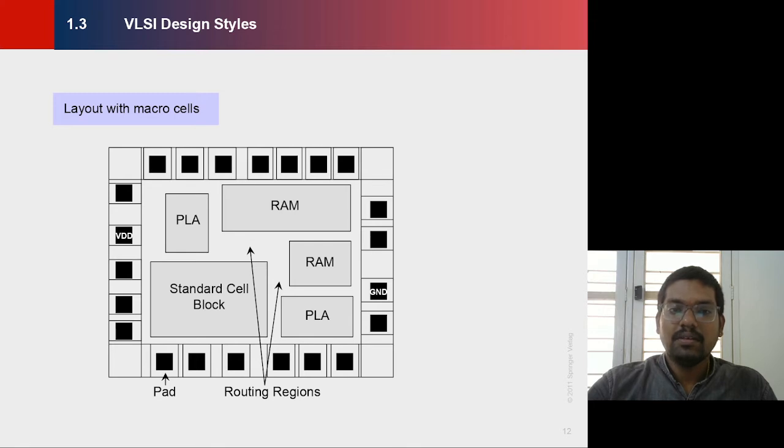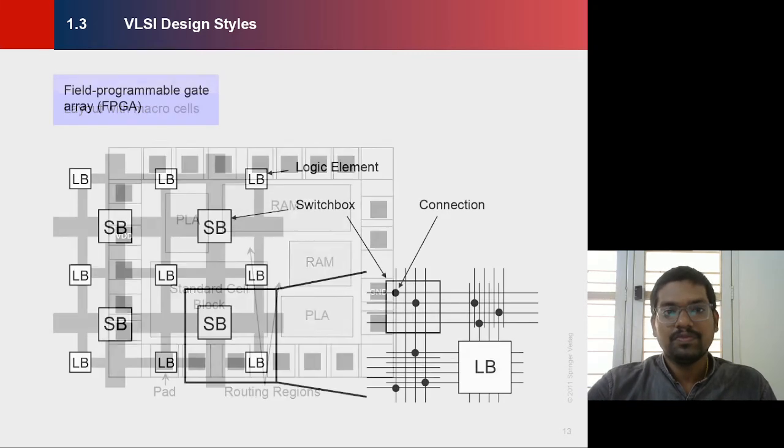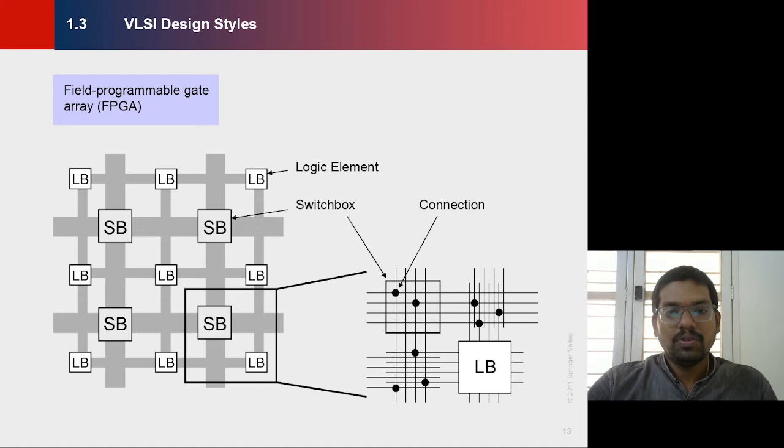And this is the layout for a micro cell, which consists of a standard block. I can tell you what a standard cell block is: it has a constant height. Heights are fixed; you can vary the width, but the height is fixed. Such cells are called standard cells. So this is the feed through logical design. This is the switching box as well as its connections.